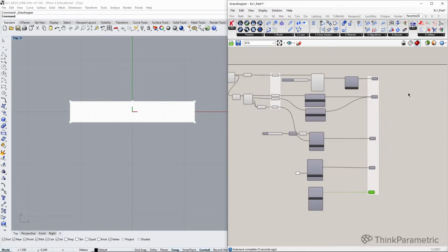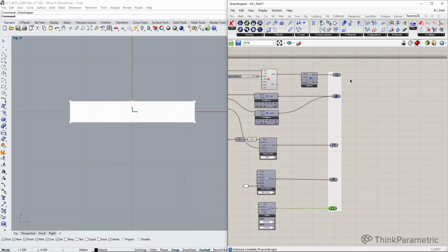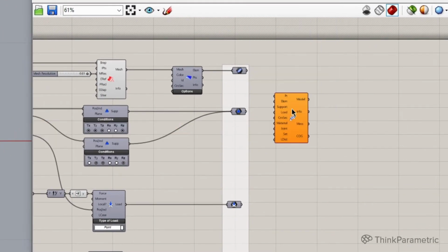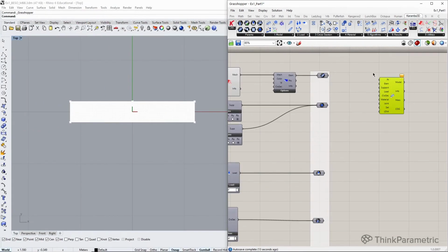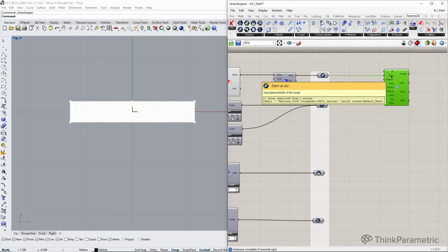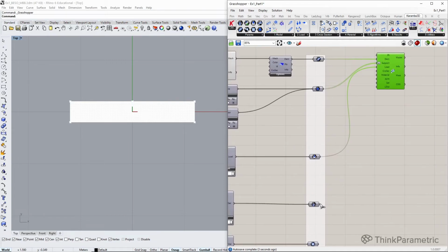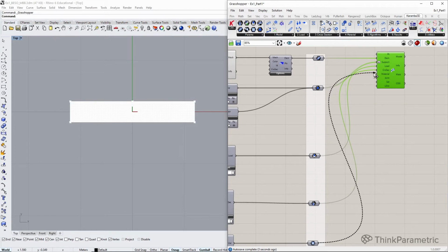And now it's a very important step, that is assembling our model. Assembly model. What we have here, we need to specify elements. So I'll go to elements. If you have more than one element, always flatten at the entrance. I have two supports that are in one list, but in case there are three, we should always flatten at the entrance. And loads is also just one load case. Then we have cross section that goes here and the material that goes here.